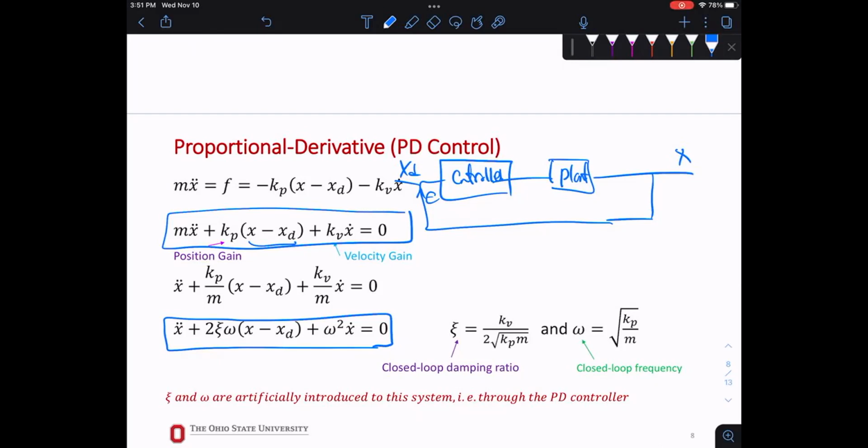Usually you can tune Kp, only use the P controller, and then pick a very large Kp, right? Create a very large damping, frequency. It might break your motor, right? If it's equal to the natural frequency of the motor, what's going to happen? Also same for here. So when you're tuning, you want to look at these values. You don't want to overload your motor. Your controller should not break your motor, right? So that's why we have to look at the closed loop frequency and damping ratio.